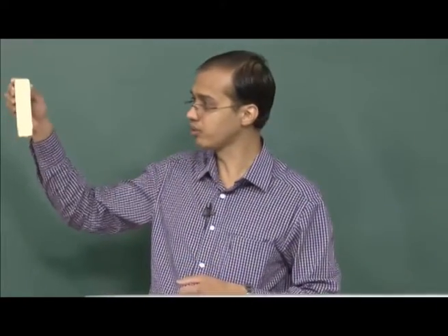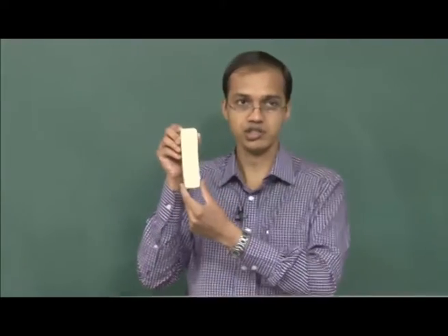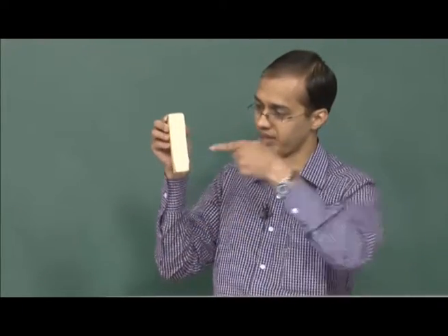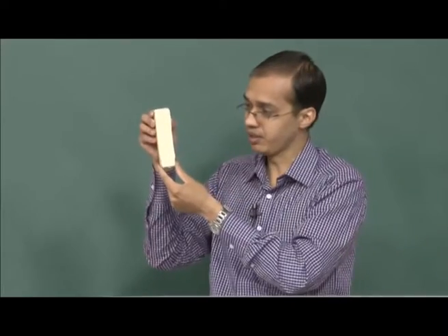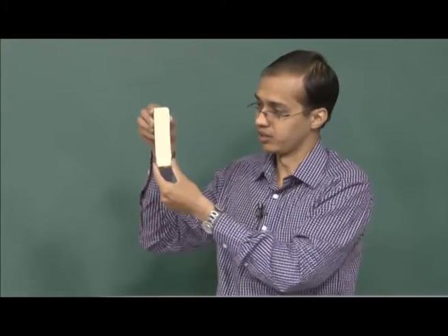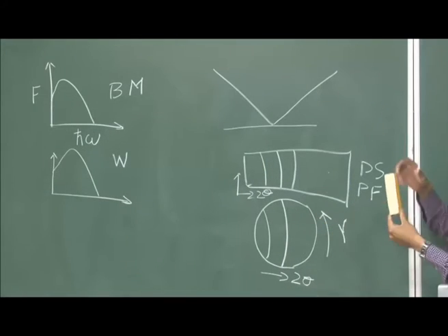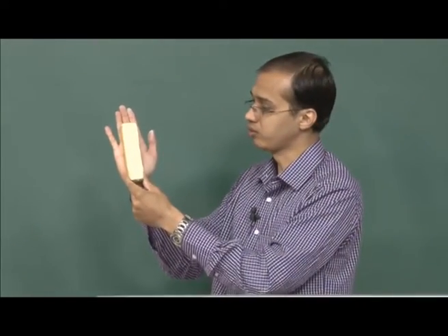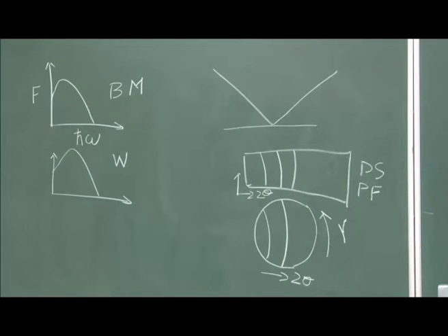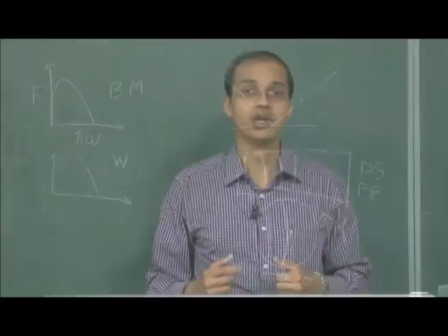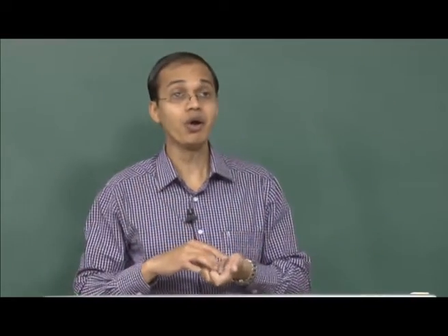So, essentially we talked about only diffraction, where the X-rays are getting diffracted, but the sample can also be tilted accordingly, and therefore you see this corresponds to diffraction not only from the planes which are directly aligned this way, but also the planes which are aligned at an angle corresponding to chi. So, I hope you appreciate that in a normal 2-dimensional detector you get a lot of information, or a much better view of reciprocal space.